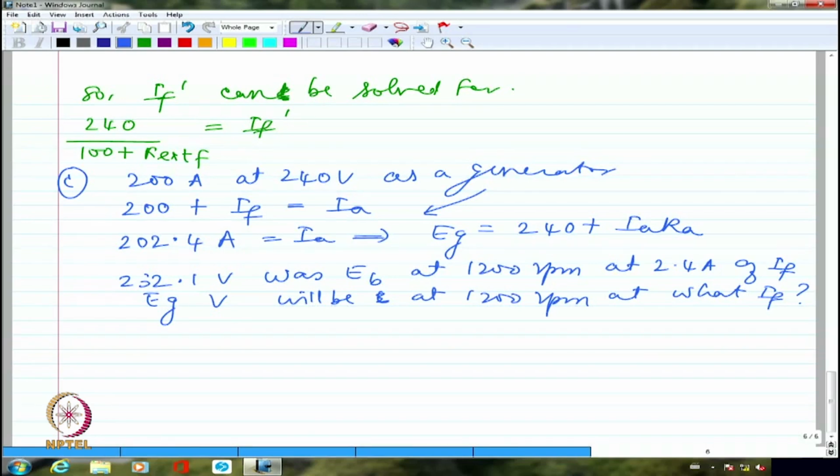Most of them work on ratio and proportions because we hardly ever give the nonlinear portion of the magnetization characteristics very often. We try to confine ourselves as much as possible to the linear portion, but if we go into the nonlinear portion, we may say, although the increase in the current is by so much, armature reaction weakens the flux by so much percentage. That's what we say.